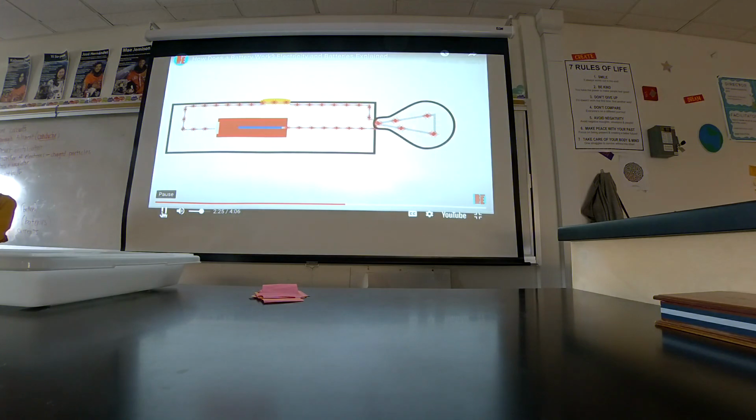We make a small part of the conductive path that the electrons take removable. When you flip the switch off, the conductive path is broken and the flow stops. When we flip it on, it continues. The switch is simply completing the circuit from the front of the battery to the back of it. This on and off switch here is the fundamental principle behind how all buttons, switches, touchscreens, and really anything